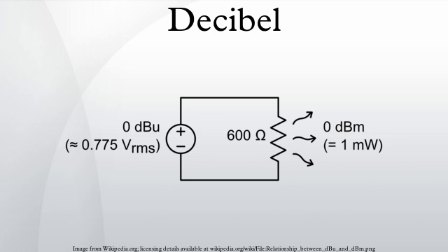That is, log(A × B × C) equals log A plus log B plus log C. Practically, this means that, armed only with the knowledge that 1 decibel is approximately 1.26 power gain, 3 decibels is approximately 2× power gain, and 10 decibels is 10× power gain, it is possible to determine the power ratio of a system from the gain in decibels with only simple addition and multiplication.